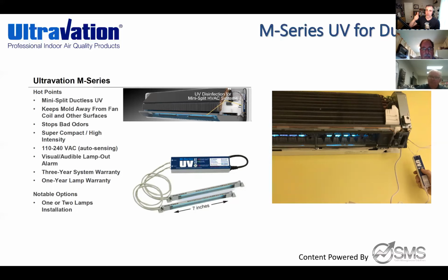It's just the filtration that they put on these shouldn't even be called filtration. I just call it a dust bunny screen, because all those particulates are getting trapped on the coil. You got a lot of moisture going on. If you didn't measure the room for load, you might have too much moisture going on. And again, moisture plus particulates.